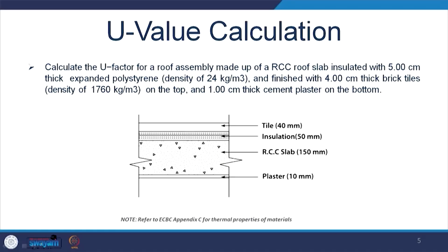Now, how do we calculate this U value? Often the U values or the resistance or conductivity values for individual materials are available, but for the assemblies it is not available. So in ECBC the method for calculating the U value for an assembly is also given. Let us quickly look at this calculation here.